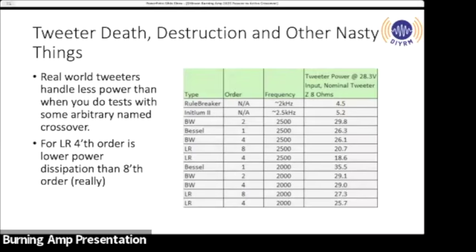Okay? But if I use the real filter functions of a real speaker, and these are 2 of my designs that you can get for free on my website or on the Facebook page, and I used the actual voltage transfer function of those filters, your 100-watt continuous pink noise into that speaker yields about 4.5 or 5.2 watts to those tweeters. Lo and behold, that tweeter would most likely survive-ish. Okay? Because these speakers are never meant for that length of duration of sound, right?